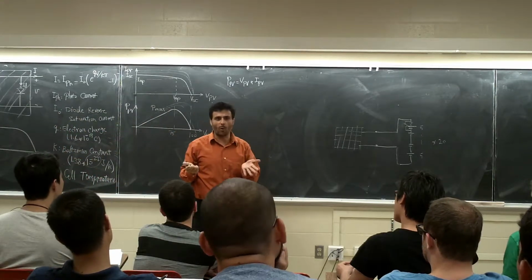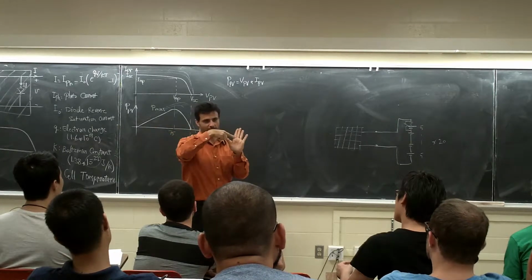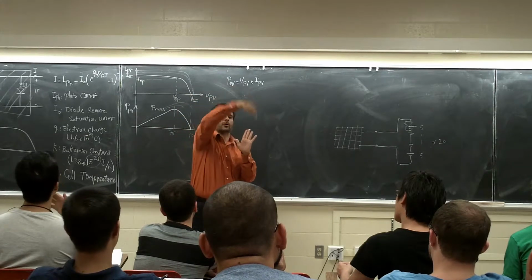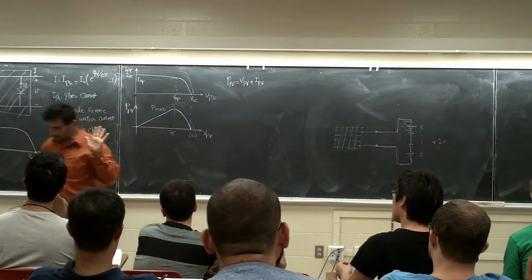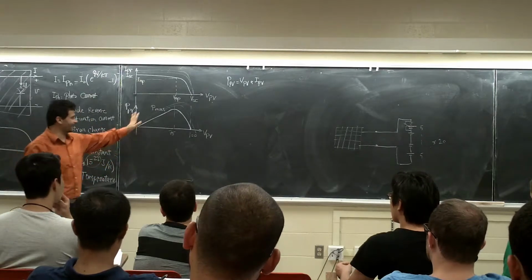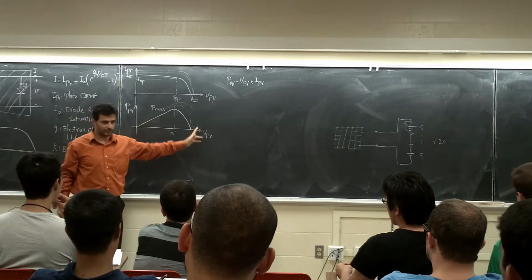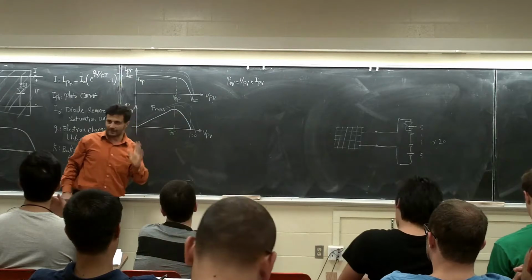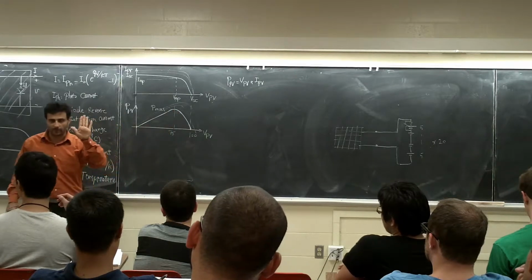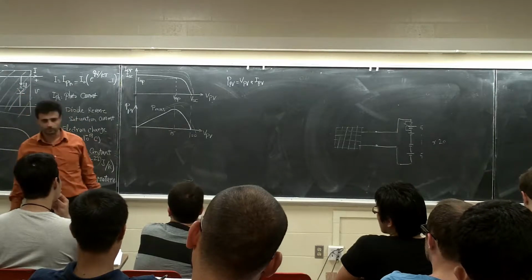But if, for example, it's a home, you're not going to put it there. You put it here. So morning is a little bit this way, and afternoon is later, this way. For example, from 11 to 2, you have something almost perpendicular to the panel. You know what I'm saying? They call it maximum power point tracking 2-axis. One axis is electrical: where I am, I have one of these curves, and I want to go to the best point I can stand. The next axis is, hey, I want to get the best of the sun, so I'm going to tilt my panel to face exactly the sun. You know what I'm saying?